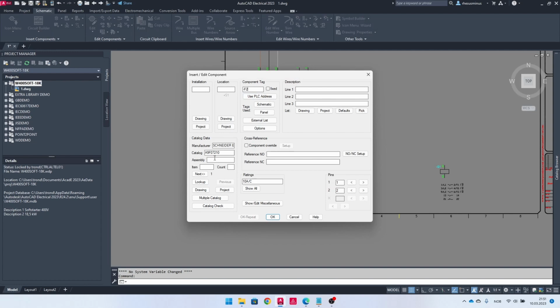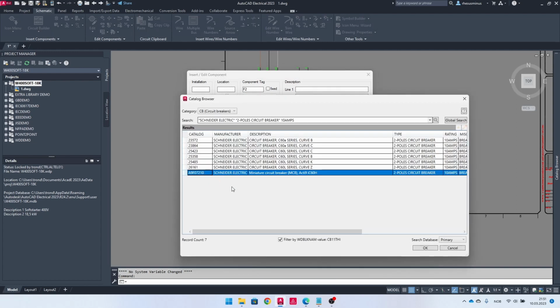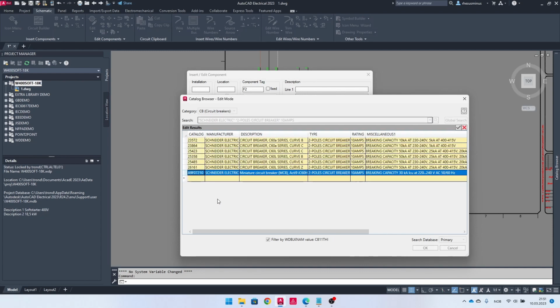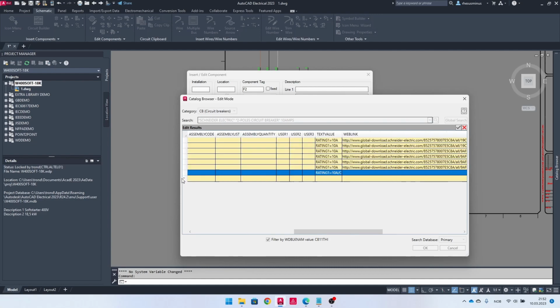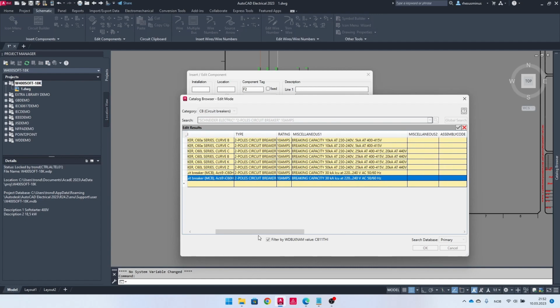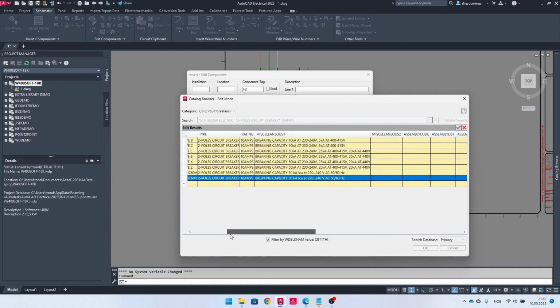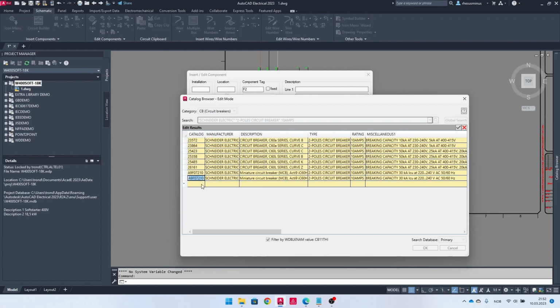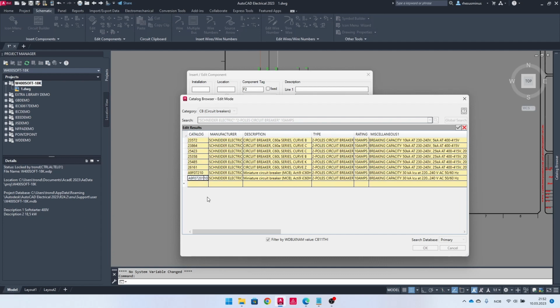And this one should be the 10 amps, this should be the 1 amp version. So I will edit the parts database, I will copy this row, paste it in here, and I will just make the changes that I need here. That would be a 0.1 at the end instead. Plus 2 poles, and it should be 1 amp.